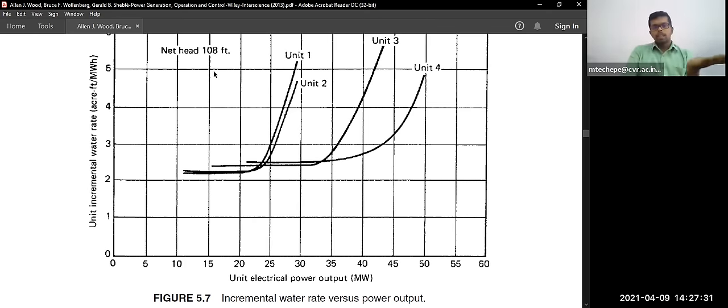Say, for example, we forecast 13,500 megawatt today, but the actual scenario, if you combine all the loads in Telangana, is 13,600 or 700 megawatts. So 200 megawatt is the deficit today. How do we manage a 200 megawatt deficit? In every area, they cut the power for half an hour, 15 minutes, 20 minutes, like that. They touch the remote areas and manage that power deficit also. So that is also there in this.